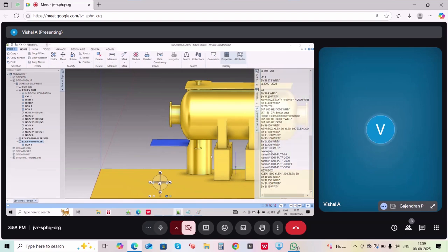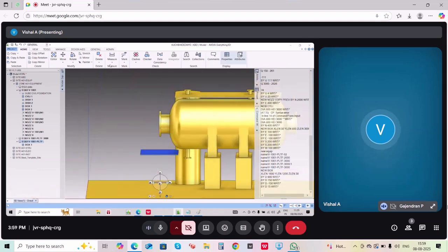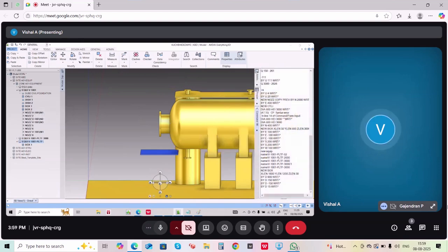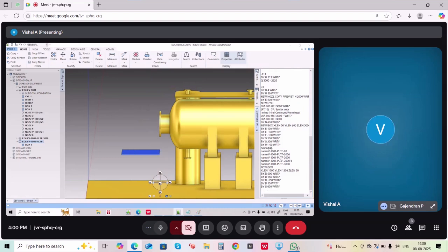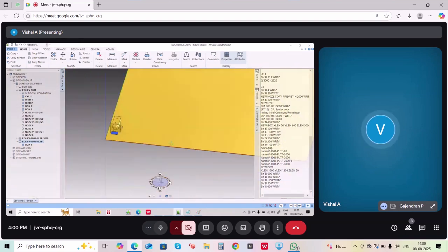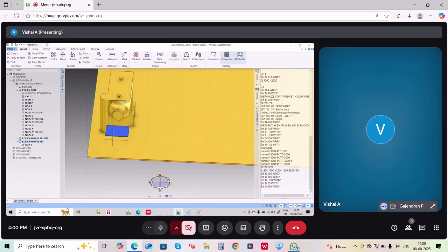So this is how it will be correct, 900 mm from top of the grating to the center of this. Then you need to measure it from the center of the nozzle to the back side of this. How much is it? 600 mm. So you need to push this box outside towards south direction by 600 mm. So by south 600 WRT slash star enter. So this is how you're going to push it back, correct? So now you know that this is the position of my platform.